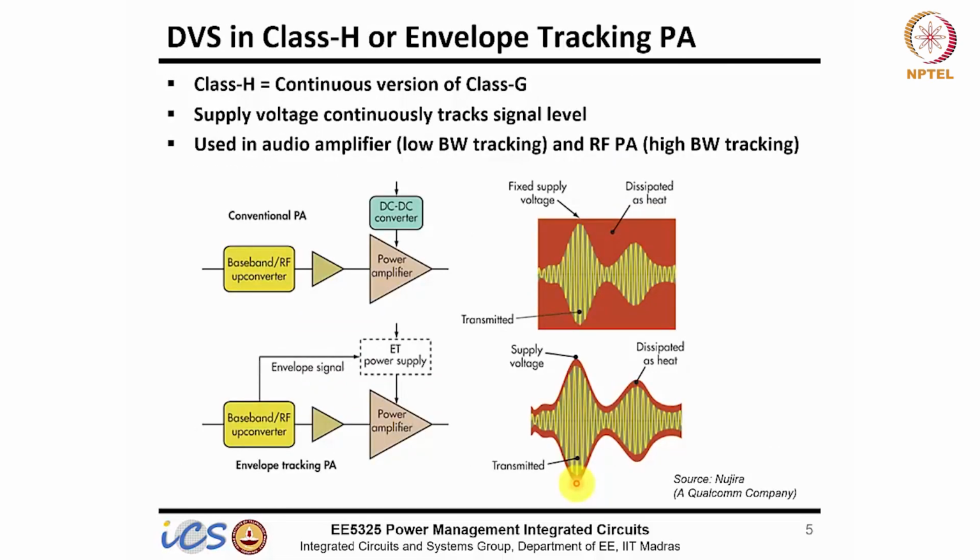The dropout voltage depends upon how you design it. If you can sustain 50 millivolt, then have 50 millivolt. I have shown a PMOS, but these amplifiers usually have both N and P, push and pull, so it will have both source and sink, and you have to regulate the voltage of both. If you want only one side, whatever the minimum voltage it goes to, you always keep your supply 100 millivolt higher than that. So your reference will become your signal plus 100 millivolt, so your Vref will always regulate your output to Vin plus 100 millivolt. That's what you have to do.